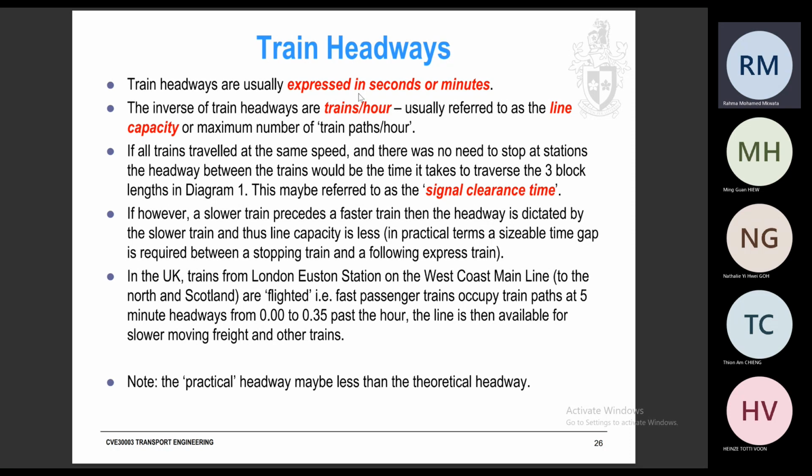How much time do you give between the intervals of 2 trains? If your service line, let's say you give it at every 10 minutes, you'll have 1 train arriving. That means for the entire hour, you have like 6 trains arriving at the station. That's actually the headway.